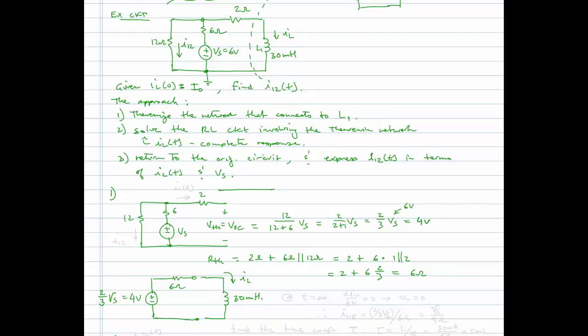When I look at this circuit, I think, okay, what will the steady state current be? At some point when the current is no longer changing in time, and I expect it's not going to change any longer in time at some point, maybe at time infinity, because I'm driving the circuit with a constant voltage source, a constant source. So at that point, di/dt is going to be 0. So at t equal infinity,